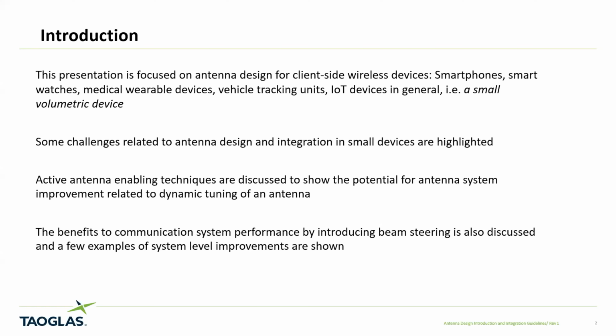As we bring 5G on, the value added from the antenna system side is going to come from not driving a single antenna, but going to higher orders of MIMO, and introducing or continuing to implement beam steering in either a massive MIMO array or as a phased array.